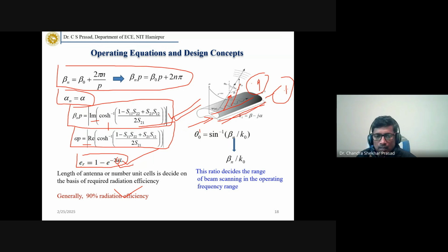Here we will not use the term attenuation constant, but leakage constant. So if your alpha is relatively high, the length L of the structure will be relatively low, and so on. We can do some trade-off depending on our requirements, fabrication limitations, space limitations, and so on.